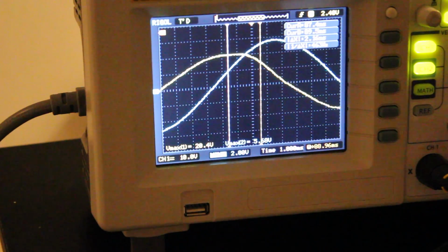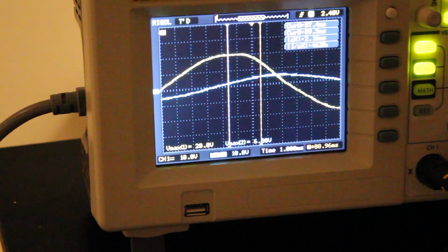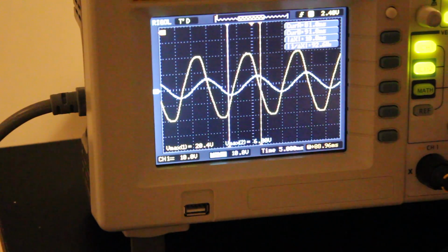So not too bad. The cutoff frequency of that, what is the cutoff frequency of that? 1 divided by 2 pi times 1e3 times 10e negative 6 gives me a frequency of 15.9 hertz. Okay, so we're way over that. We're way beyond that. So that's why when we bring both of these scales down side by side, our gain has fallen off so badly. So we're filtering that pretty well, actually.